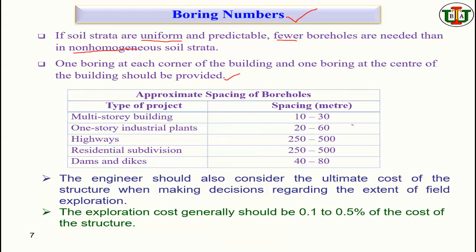If it is multi-storied, you can consider 10 to 30 meter spacing maximum. If it is a one-story industrial plant, like a very large area, you can consider 20 to 60. Sometimes you will find a very long project. Even if it is a highway, you can go 250 to 500, right? So these are some examples.